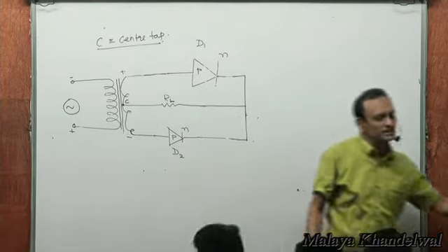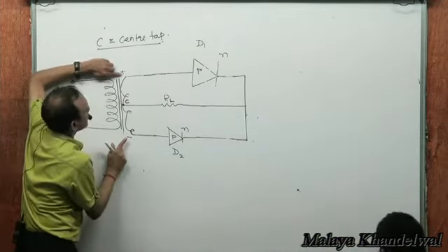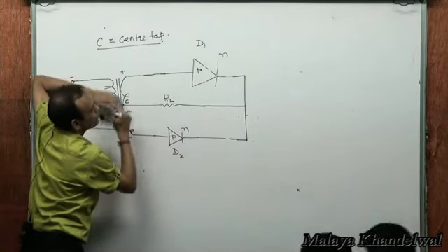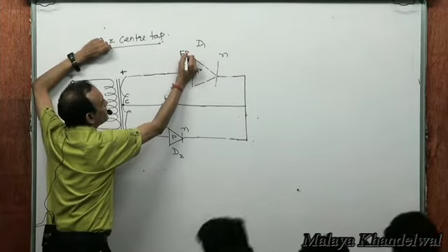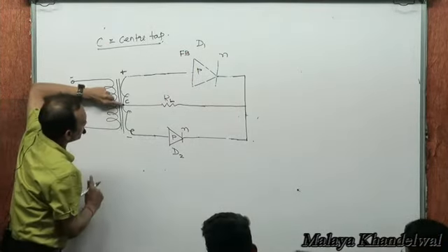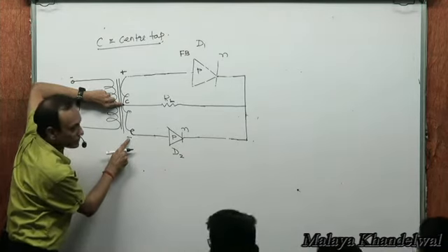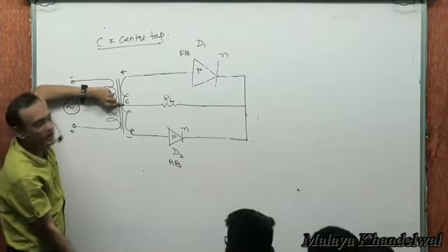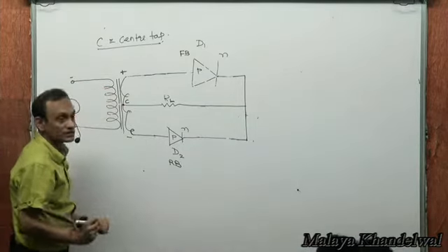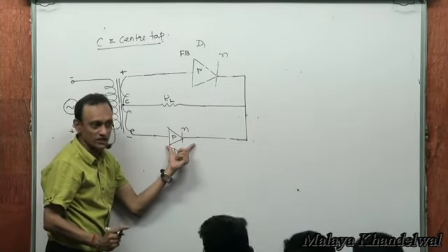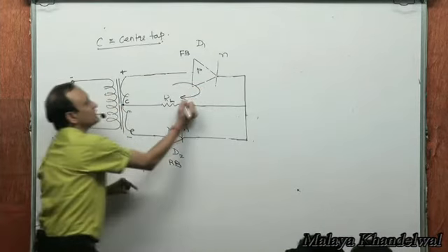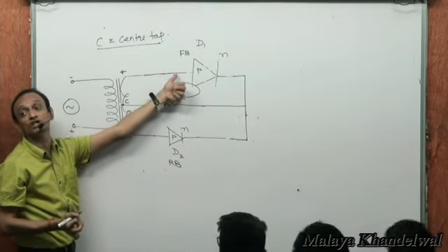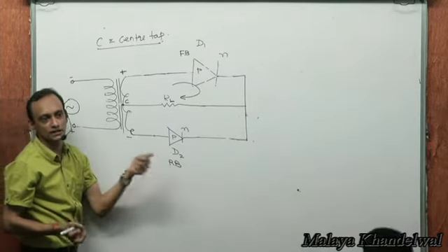Okay. Now please understand, very simple. There is one half of the cycle in which this is positive, this is negative. That means P connected to the positive terminal, this will be forward bias. Now, between C and this, which is more negative? This is more negative. And P connected to the negative terminal this time, so this will be reverse bias in this arrangement. Which means this will disallow current because it's in a reverse bias mode. This will allow current. In one half of the cycle, this allows current and this disallows. Why does this allow? Because this is in the forward bias mode and this is in the reverse bias mode. Good.